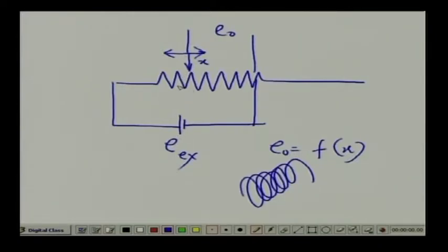That type of case does not arise in the LVDT, because I have a core and a bobbin, and inside the bobbin this core is moving, is it not? So, there is no physical contact. So, life is almost infinite; you can say the mean time between failure is very high. Moreover, resolution is also high, because the resolution value here is very small. Small means good, extremely high.